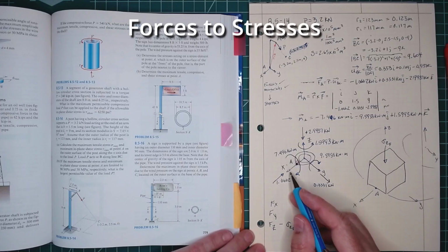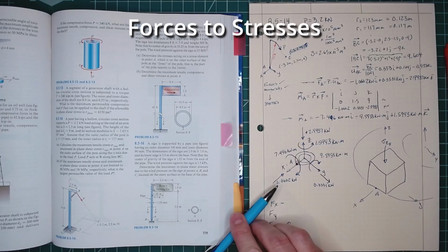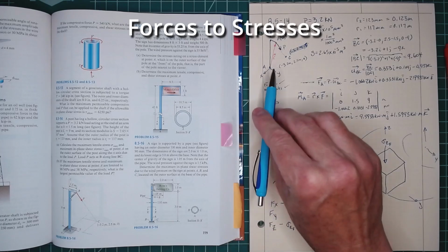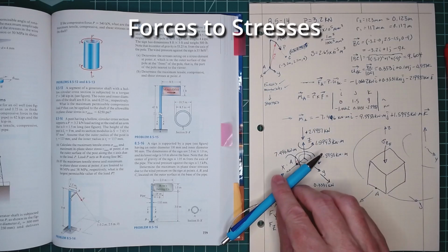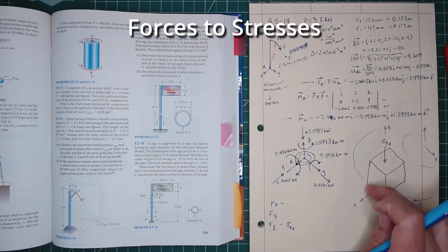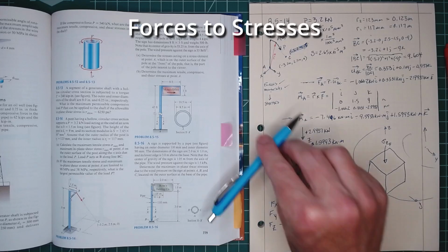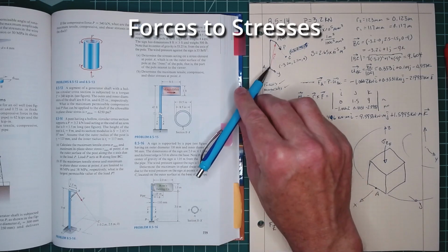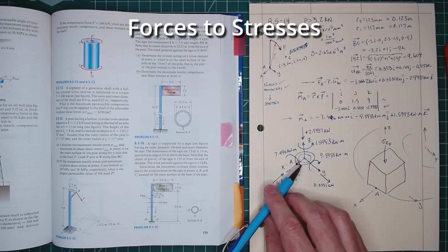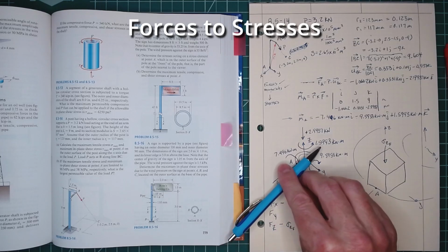force in the x direction. Okay, so what is this force? What stresses is that force going to create? Well, if we look at this, this is not necessarily a direct shear condition. There's no force acting on this face, so there's no compressive sigma acting on that face. So we might have a shear stress. In this case, we might have a shear stress due to bending on there. And if we think about that, we have a shear stress going in this direction.